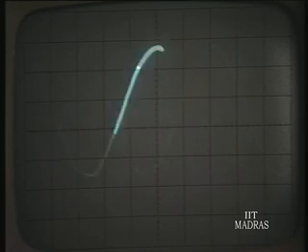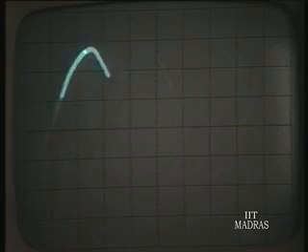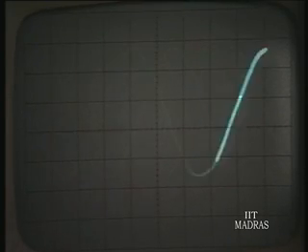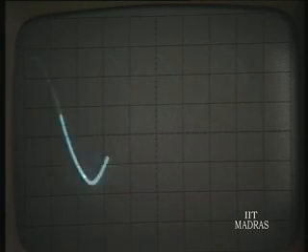And the deviation produced at the input should be the same as that at the output. If it is a low frequency modulating signal, the deviation produced at the output is going to be the same as the deviation produced at the input. Now, she will change the frequency of the modulating signal. It is reduced, you can see the frequency is reduced, very low. Increase, the frequency of the modulating signal is increased, and this is the FM detected output.